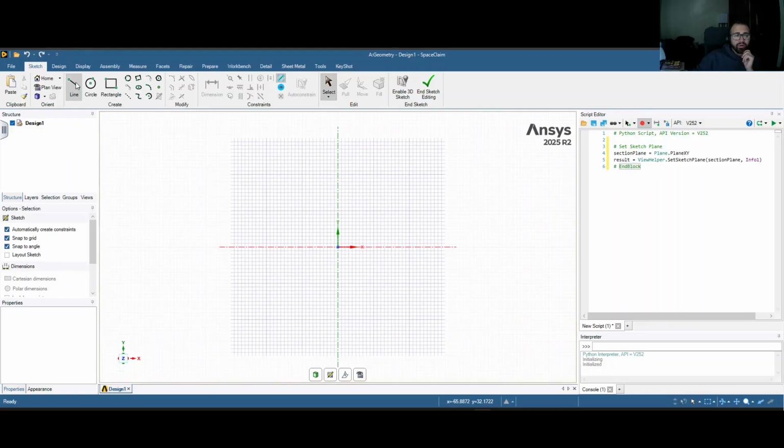Now we need to have a set dimension for the artery length from the inlet to the outlet. And one advice here, basically try to reduce the constraints that you are using, because not every constraint is reproducible inside Ansys SpaceClaim. And I'm going to show you later what I mean by that. So basically just any dummy line here.